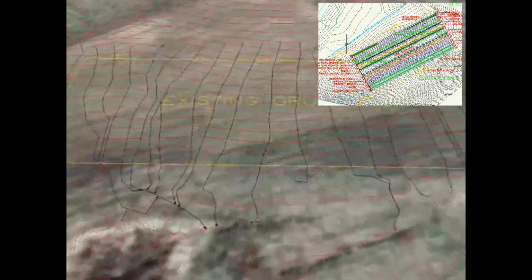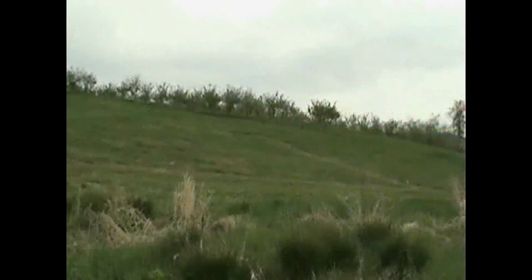So this is all shot in Civil 3D AutoCAD with total station equipment and GPS equipment, a combination of the two. And then that was all imported into AutoCAD to develop a 3D mesh model that we could then develop topographic data from. From that topographic data, I was able to develop a water drop projection, which you can kind of see in that profile drawing there.